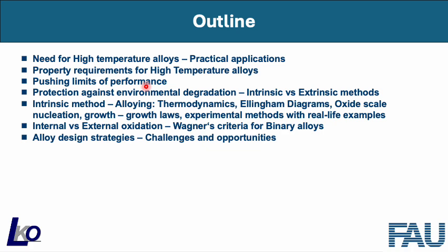And then we will briefly talk about the Wagner's criteria for internal versus external oxidation, how we like to have an external scale form rather than forming internal oxide precipitate which might degrade the mechanical integrity of the components.